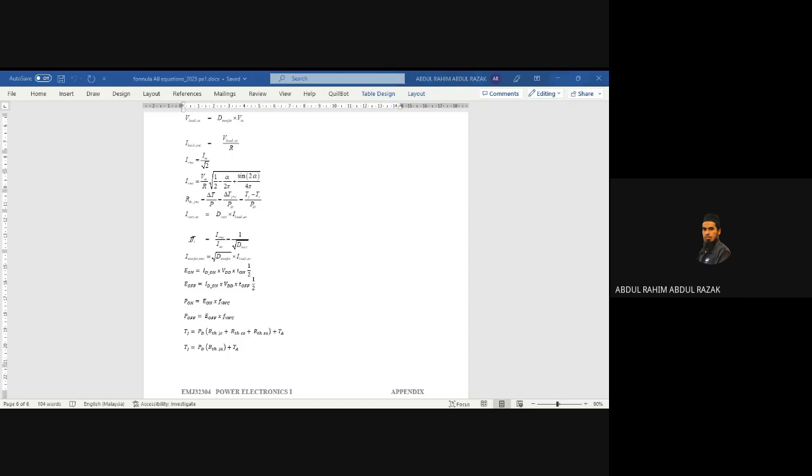Then what is the required voltage that the device can withstand? Maybe it should withstand around 400 volt. So we take the next step of voltage range, which is 600 volt. And this is to play safe. To play safe, we put one range higher to evaluate our device.